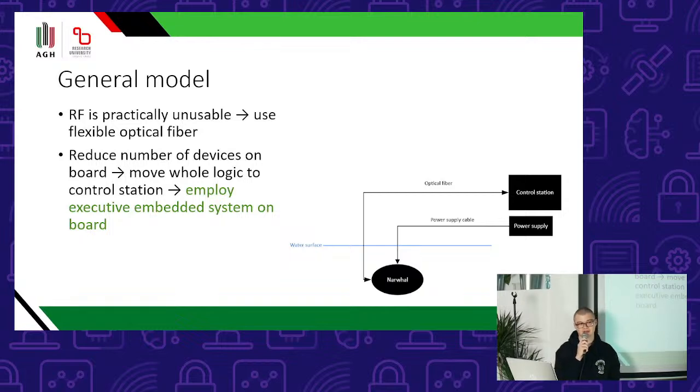Because the attenuation of the radio waves underwater is actually huge, and we can't use any kind of protocols you would normally use to connect with any device on even a few megahertz, not to say anything about Bluetooth or Wi-Fi that work on gigahertz.